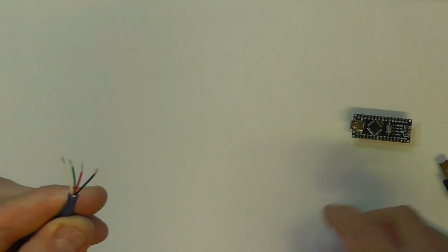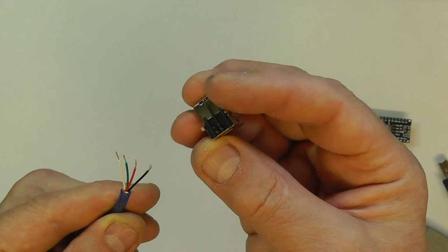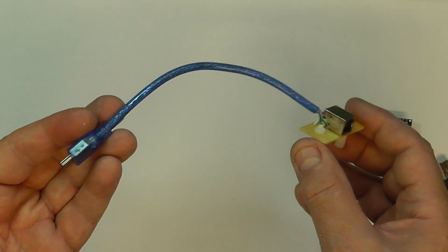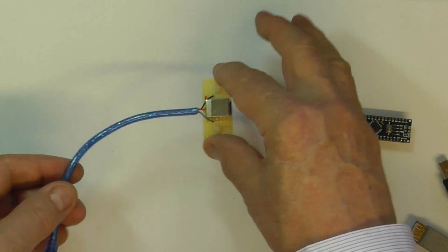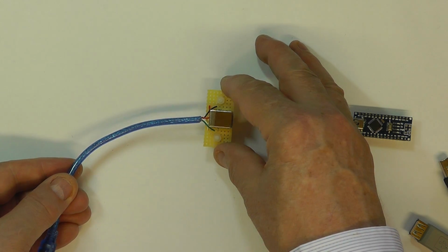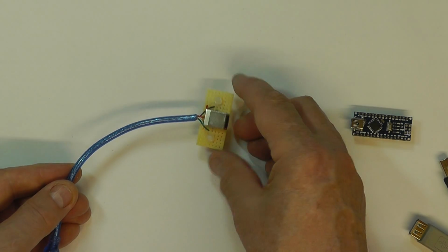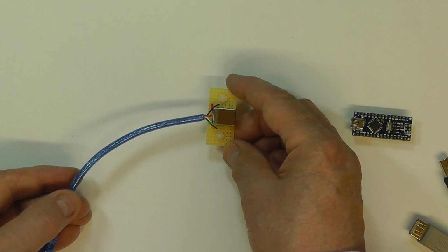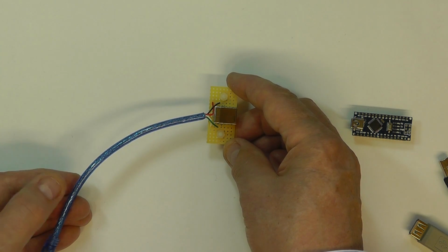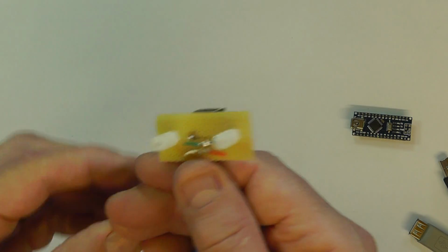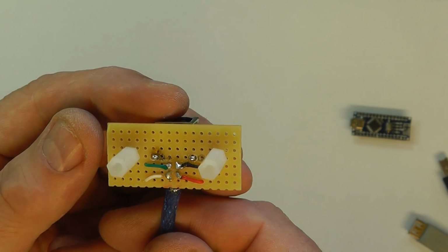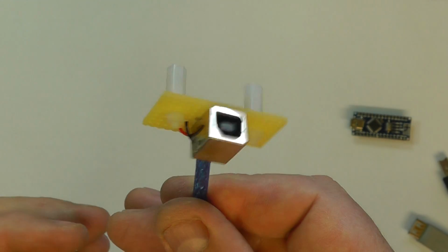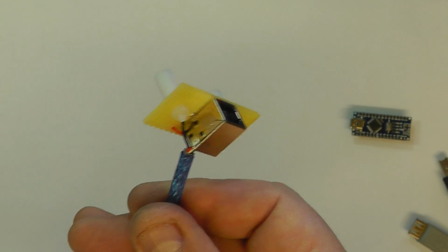And I'm simply going to solder that onto the USB-B socket, and this is what we have here, it's just soldered onto that, and then that's going to bolt into the case, and then we've got permanent access from the outside of the case for logging the data, and also we can use it for programming or reprogramming the Arduino Nano. So that's the underside, you can see the connections there. But I'll give you the details of this as a download information sheet.